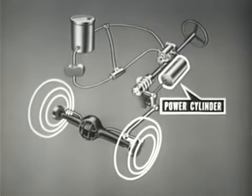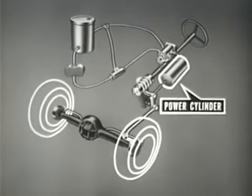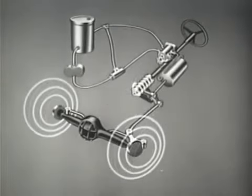The power cylinder converts hydraulic pressure into mechanical force, which in turn actuates the Pitman arm shaft and lever and the Pitman arm, turning the front wheels of the vehicle through the steering linkage.